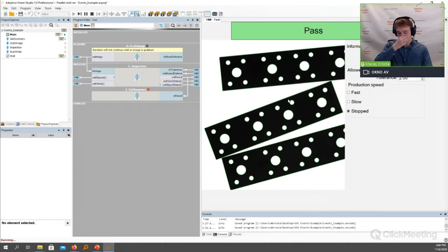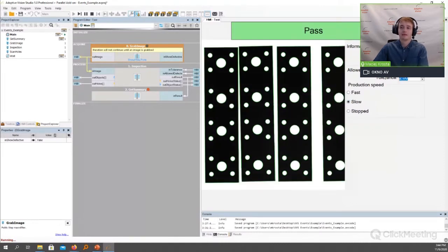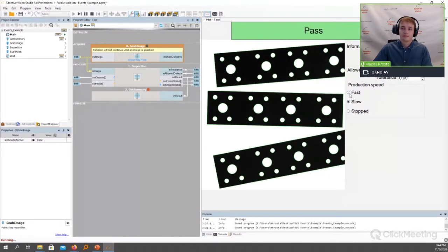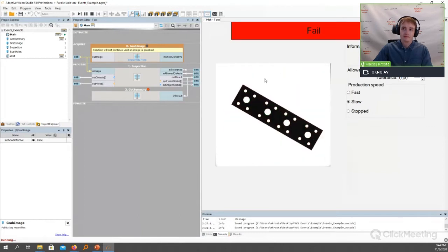However, it is important to note that this program is running synchronously with the images. That means that when there is no incoming image, the program will wait for it. In other words, the program will not execute, it will be stopped when there is no image. Which means that if I were to change the tolerance to 0, it will not have an immediate effect.